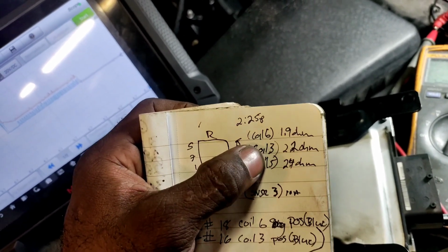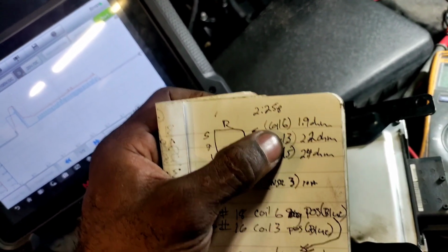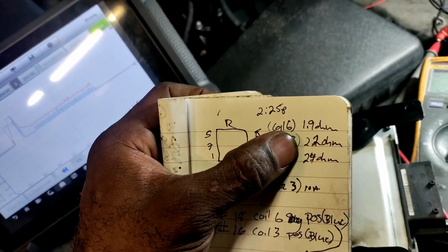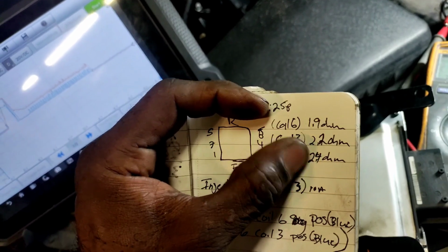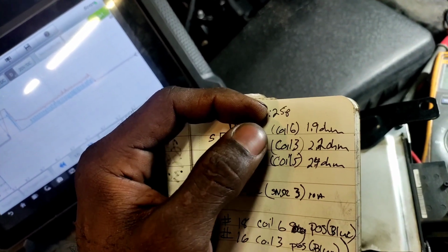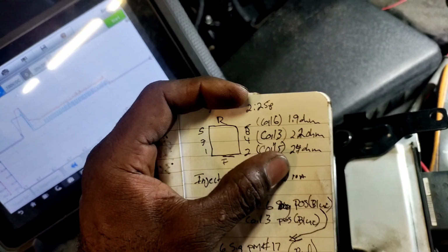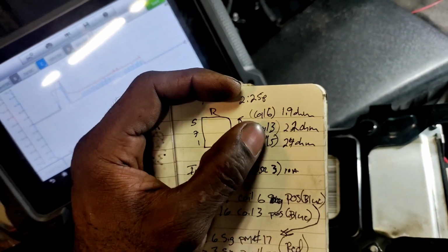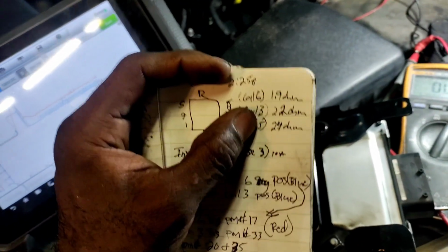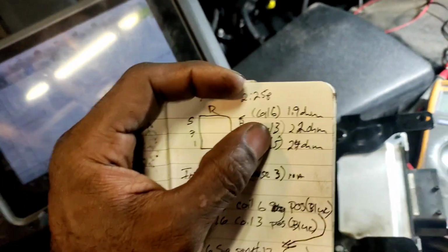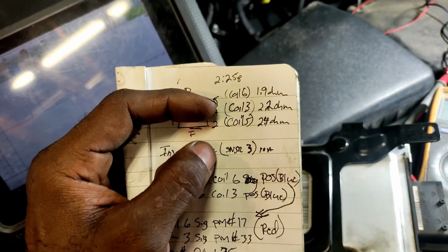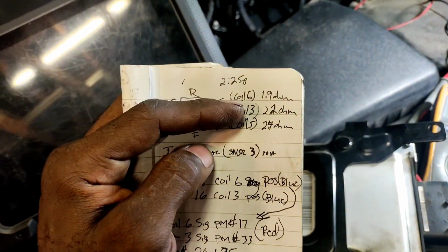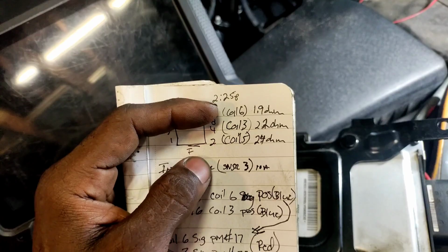The last little bit I did wind up checking. I just wrote the time down to see how long it took me to assess this car. I took resistance values at the very end, and everything was fine. With a 180 degree engine, you're supposed to take them at 70 degrees. I'll put the proper factory specification in the video, but this is a hot engine, and like I say, everything works fine. Number 3 is consistent with 6 and 5, which didn't have any issues.